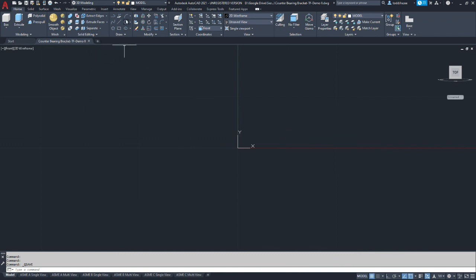So our primary feature is going to be this circle, and we're going to place it on the origin. A lot of engineers and drafters don't think about this, but the machinists that may set up to machine this part will develop their CAM toolpath off the model itself. So if you place the critical feature as your origin, it helps them control the tolerances based off that when it comes to machining the part.